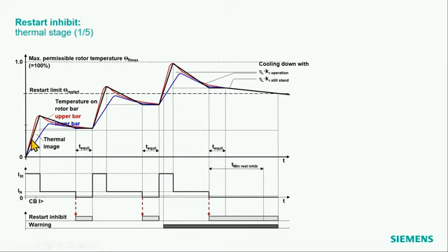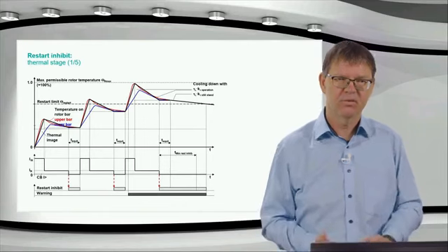And here we calculate the temperature, and what we see now here is, or what is indicated is, that temperatures are not equally distributed in the rotor. So if you have a look on the rotor bar, then in the upper bar, the temperature is higher than in the lower bar or the lower bar end. So there's a range of temperatures. This does not pretty much bother us because this is all covered by the data we get from the motor manufacturer. The motor manufacturer says, okay, we can do 3 starts from cold, so we don't need to care if there is a higher temperature or not. This is covered by the statement of the motor manufacturer.